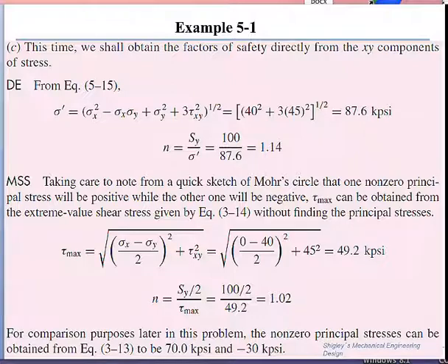And in C, we do not do the Mohr circle transformation. We go directly to sigma x squared, sigma x minus sigma y, sigma y squared, and then we add 3 times tau xy squared. That's a pretty fast way to compute the von Mises stress of the material and compare it to the yield point, giving us a factor of safety of 1.14.